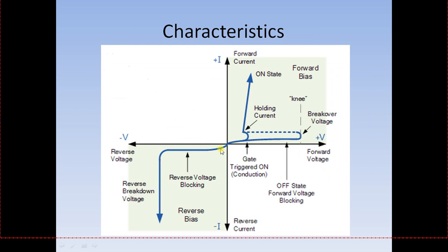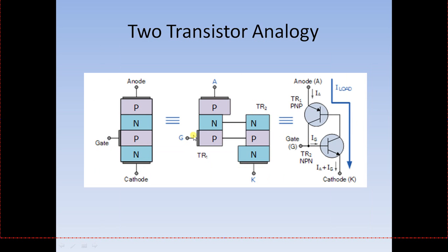It is similar to that of the diode. So if you give a reverse voltage to a thyristor, you will not get conduction, and it is seen in this graph, in this part. You keep on increasing the negative voltage, your current remains very small, and these small currents, even over here and even over here, are actually provided by the minority carriers. Now, what are minority carriers?